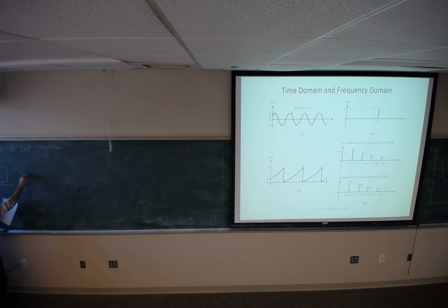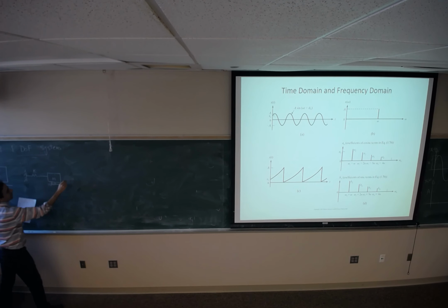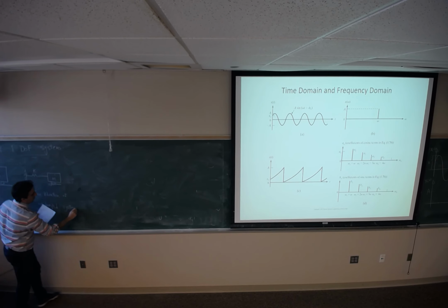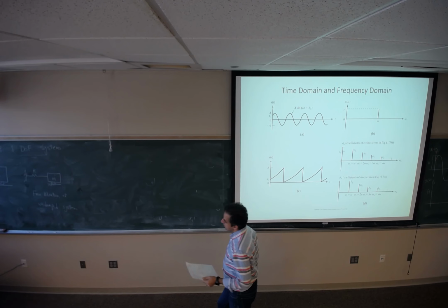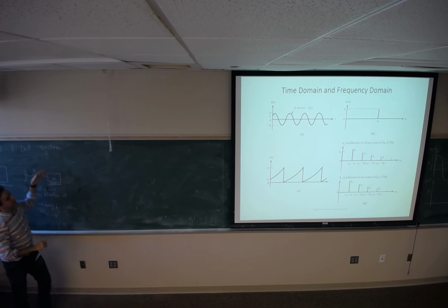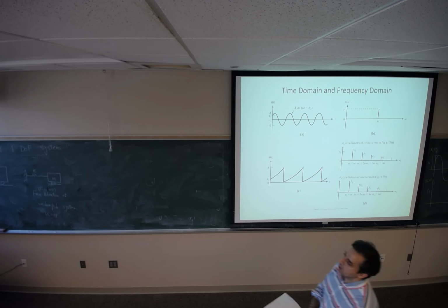I will start with the system with only mass and spring, K and M. We call it an undamped free vibration system. Free vibration means F of t equals 0. Undamped system means the damping constant C equals 0. And 1 degree of freedom, we don't need any more coordinates to define the system.